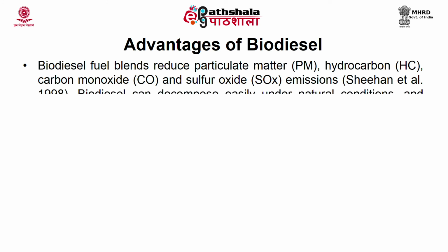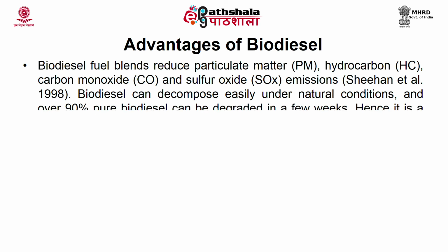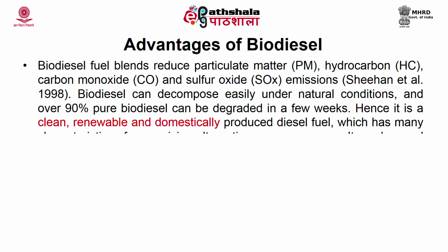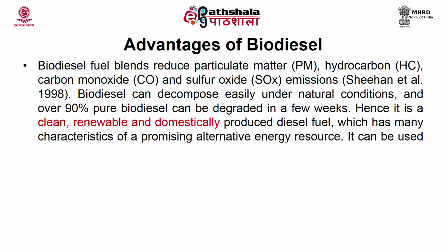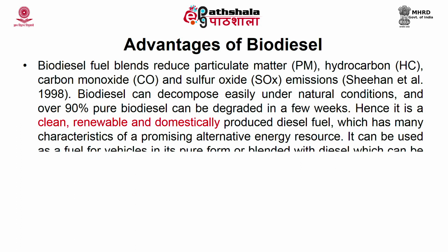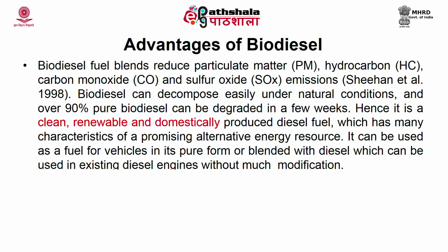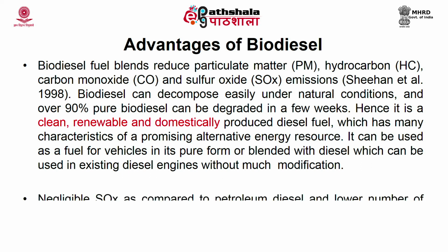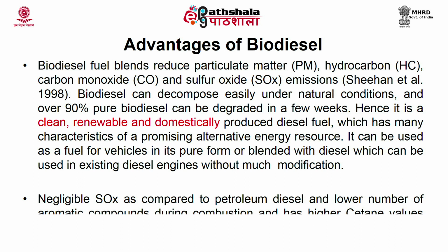You can see that the biodiesel fuel blend reduces particulate matter, hydrocarbon, carbon monoxide and sulfur dioxide emission. It can decompose easily under natural conditions, and 90% of biodiesel can be degraded in a few weeks. Hence, it is a clean, renewable and domestically produced diesel fuel, which has many characteristics of a promising alternative energy source. It has negligible SOx emission as compared to petroleum diesel, which has sulfur content in the fuel, and it also has higher cetane values than diesel fuel.